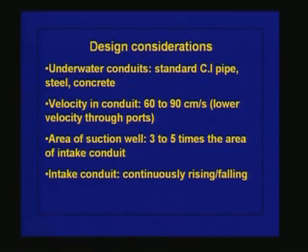Again, the velocity in the conduit should be around 60 to 90 centimeters per second. The suction well is providing some kind of temporary storage. So the cross sectional area of the suction well is another important consideration in the design. This should be around 3 to 5 times the area of the intake conduit.